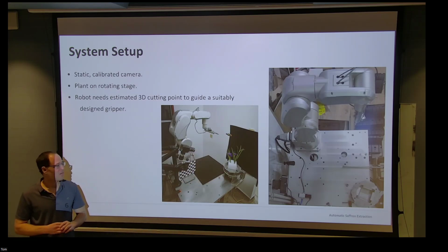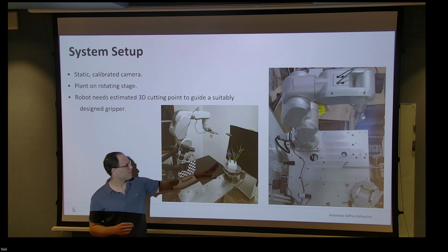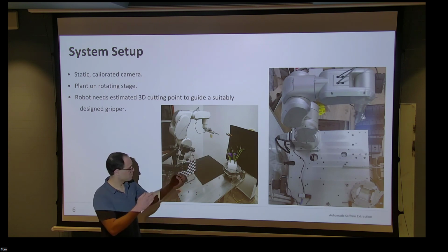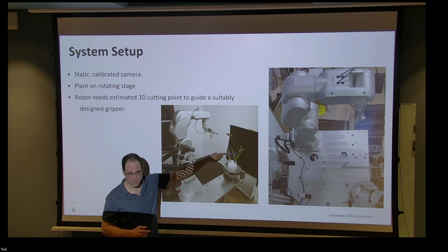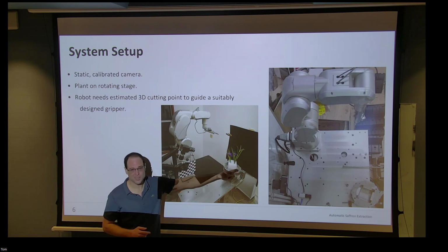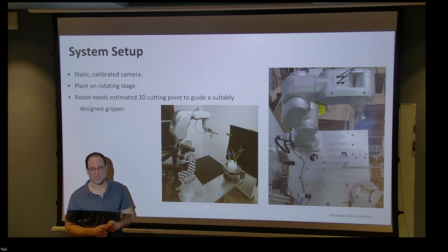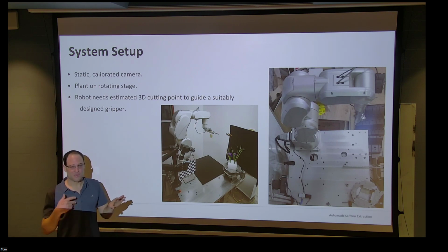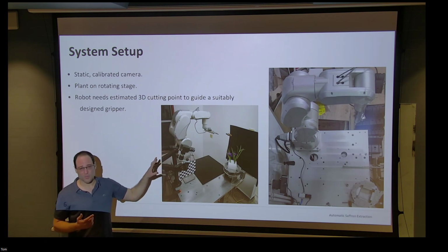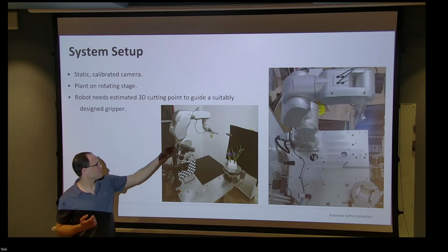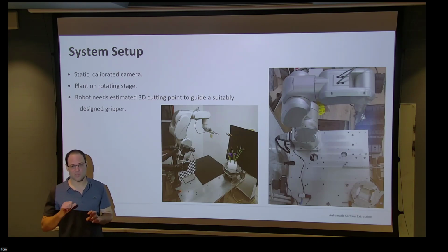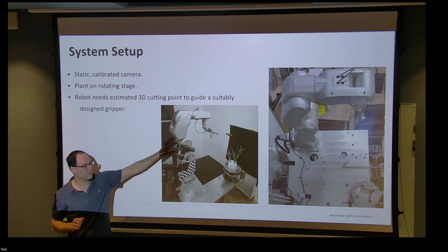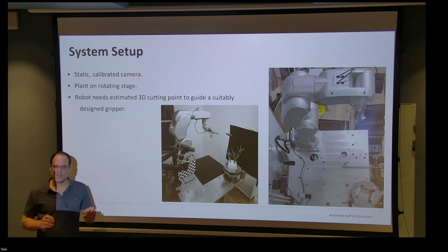What I did, I put the calibration board here, and I brought the robot in a vertical way as we use it, and put it here, telling it this is the point now. Go to here, this is the point now, and I did a simple calibration. I didn't do it automatically, and you're right that if we switch to a simple robot, we may need to care about the calibration more. This robot has absolute position. When you turn off the power and turn it on, it will remember the location, but maybe in the future we won't have this, and we will need to do the calibration smartly.